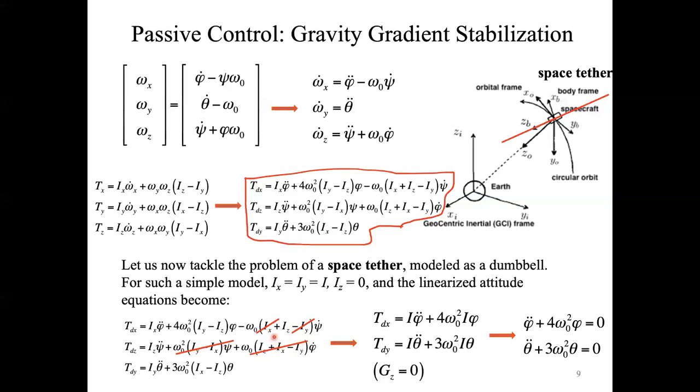So we are basically saying that the contribution of the gravity gradient is 0. So it means that if you have a perturbation along the z axis, basically the tether will start to rotate indefinitely along these axes. If you have, for example, a constant torque, you're going to have a constant acceleration of the tether along the axis. So the main purpose here is to show you that the gravity gradient is not going to give you any counter reaction to the disturbance.